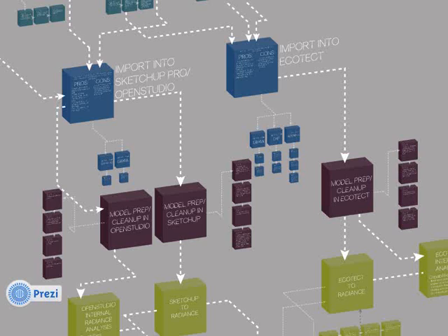So if you apply material properties in Revit and come through these processes, they should come into those transfer programs, right? Material reflectances should come in, so it takes out that step. Currently, we have not been able to do that in a smooth way, so we had to spend so much time in this step to reapply materials, make sure everything's good, and do some geometry troubleshooting. All of that is still pretty significant in this workflow. Eventually, it's going to become more streamlined where we don't have to do as much of that prep. But currently, there were some issues with every export process that we tried.